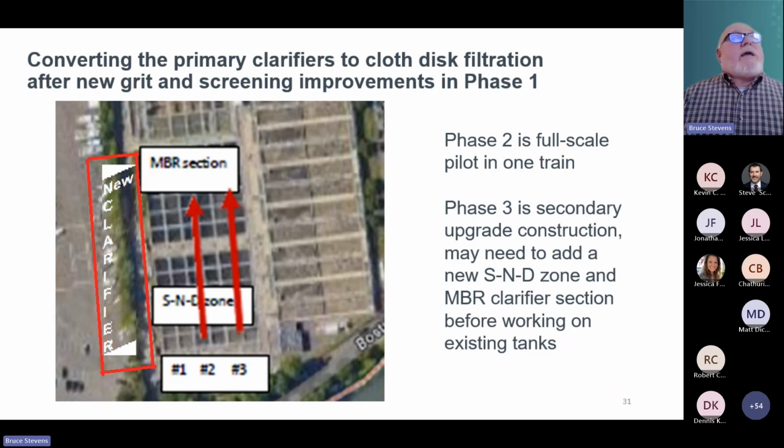The advantage we have is really the energy efficiency, the lower OPEX, when you compare to those facilities that require a lot more air to keep everything mixed all the time, whether it's the MBBR media, or keeping the MBR cassettes cleaned and scoured properly in an MBR process, or an A squared O, where you just have to keep everything moving around the tank and make sure it's completely mixed. So complete mix activated sludge, even though it's similar to what we're doing, is a more energy intensive process.